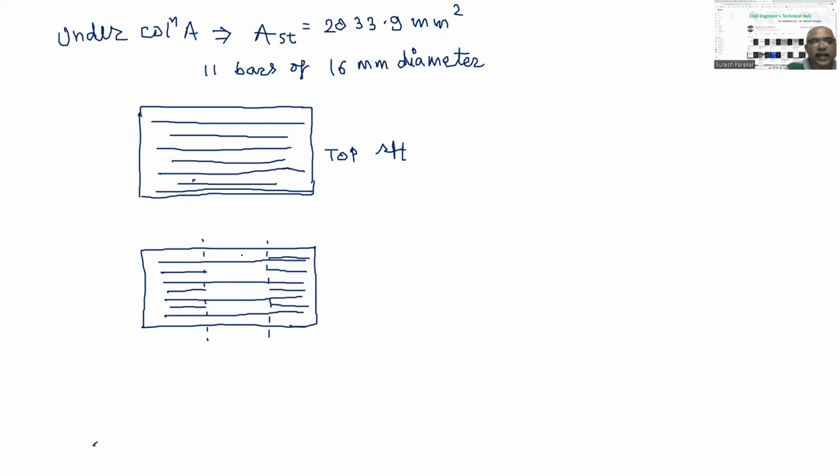And then you have to find the transverse reinforcement. For this one, you have to find the bending moment. Again we have a cantilever and UDL. We have seen this value 202.17, and we have to multiply it by length now because we are finding it along the width, so we multiply it by 5.